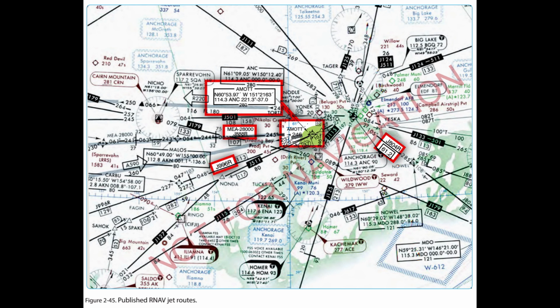When filing for a direct route flight, airway or jet route numbers, appropriate to the stratum in which operation is conducted, may also be included to describe portions of the route to be flown. The following is an example of how a direct route flight would be written. MDW V262 BDF V10 BRL STJ SLN GCK. Spelled out, from Chicago Midway Airport via Victor 262 to Bradford, Victor 10 to Burlington, Iowa, direct St. Joseph, Missouri, direct Salina, Kansas, direct Garden City, Kansas.